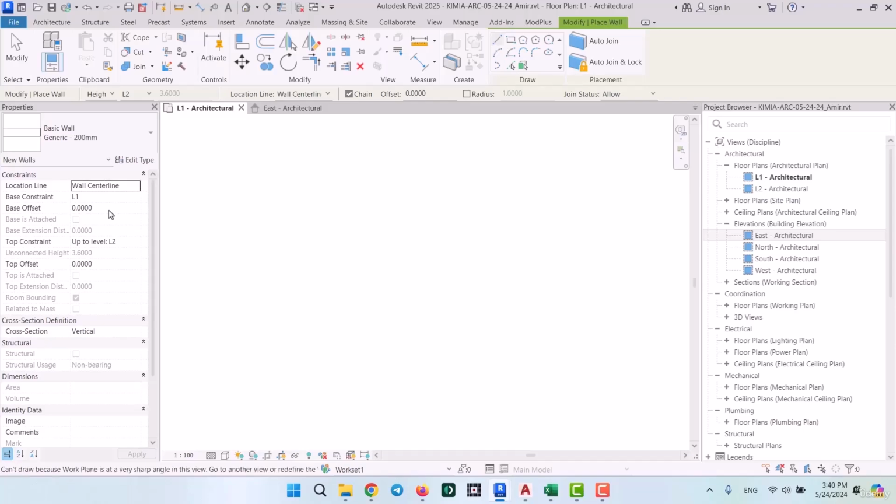But even though doing so would actually adjust the elevation of your walls, it's not technically right to do. You see, we usually try our best to not give any random base offsets or top offsets to our items in the projects. In other words, we try not to use any base offsets or top offsets unless it's very necessary. The reason for that is it may cause some trouble if you're working on a big project, because